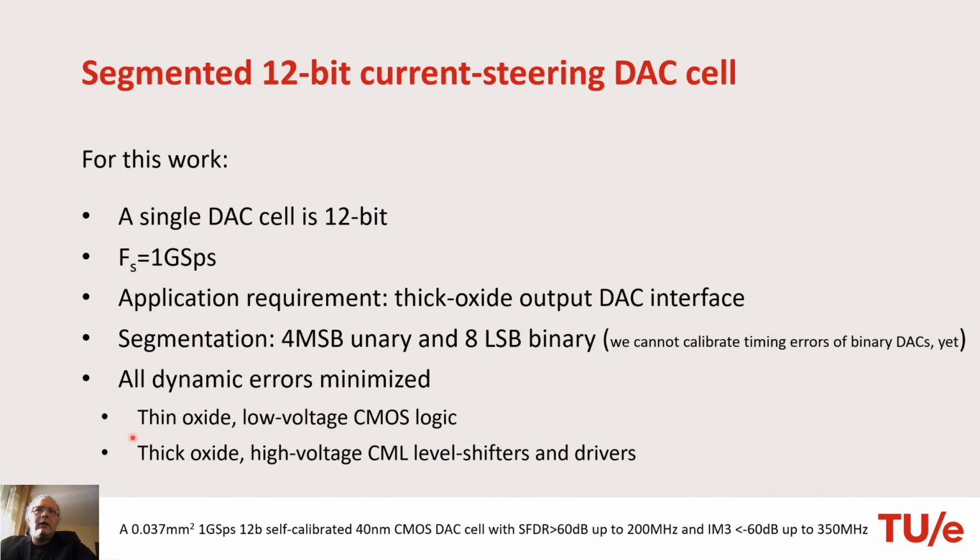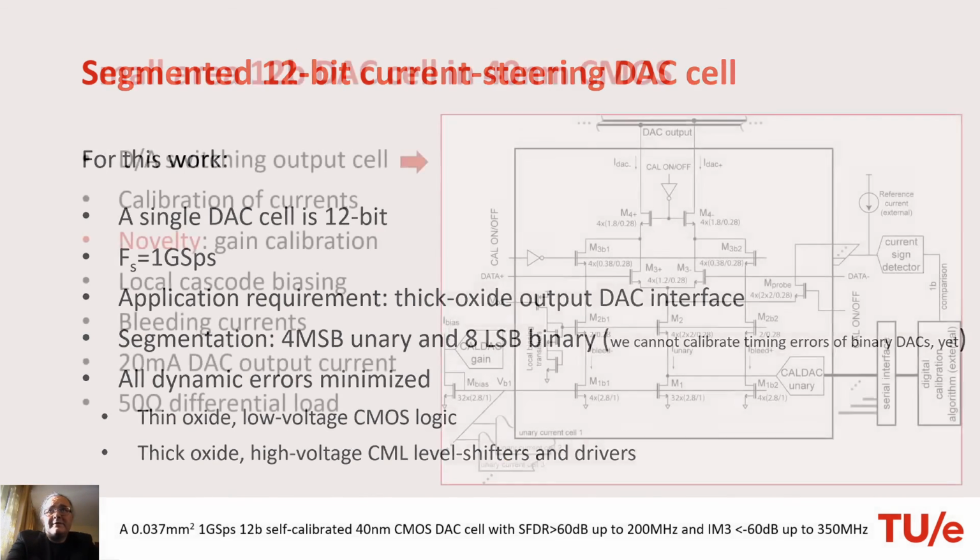And following the requirements of our applications, the output cell DAC stage needs to be in thick oxide transistors. So high voltage CML level shifters need to be used, and of course thick oxide drivers.